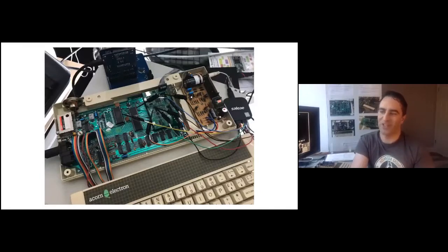The ULA generates the clock for the system, and I knew that it would generate a clock with extremely sharp edges, which would probably cause issues, especially once you plug the whole lot of stuff into the back. So I put a little filter on the output of the clock to try to smooth it out a little. I suspected maybe it was just completely removing the clock. Instead of smoothing it, it was turning it into just a little wiggle. So I desoldered the capacitor there, and then something came to life.